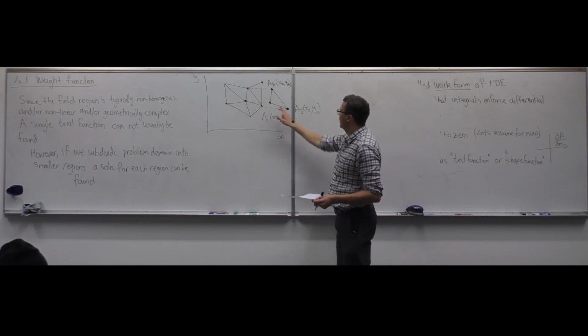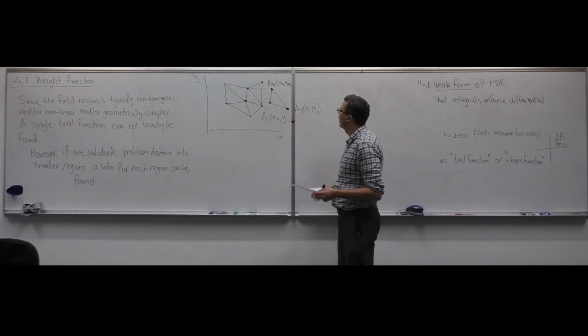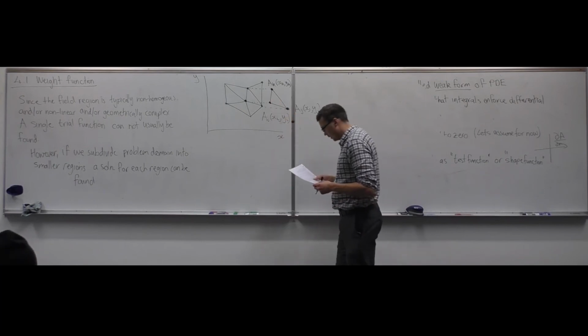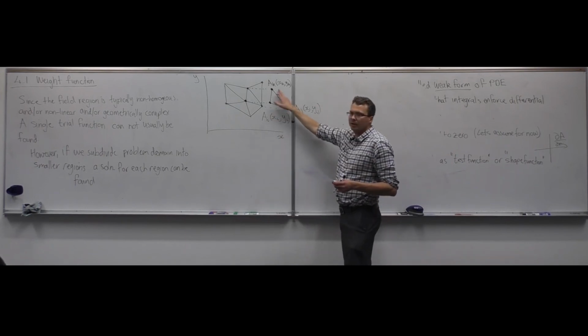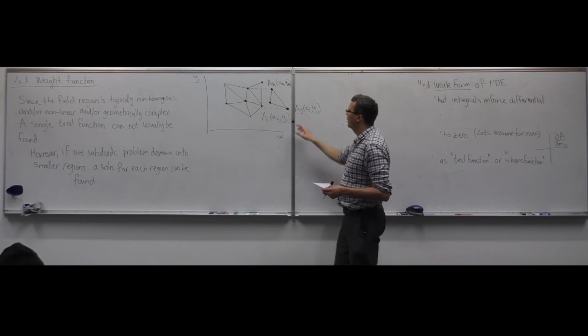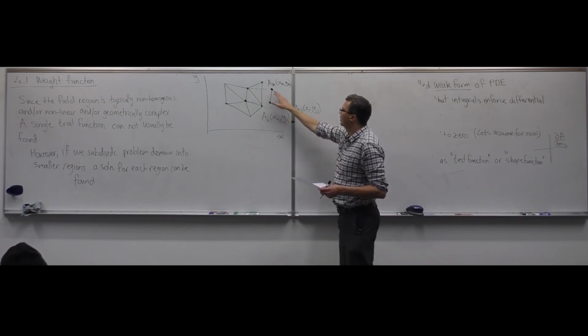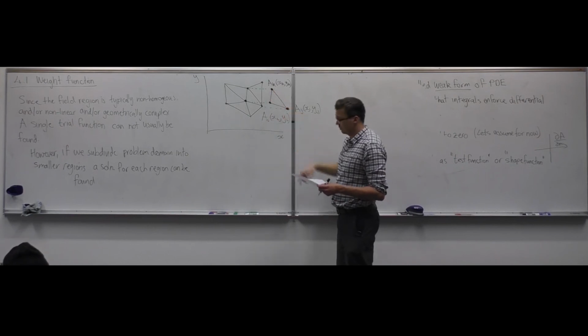So the xi and yi is a particular spatial location, and that will give a particular magnetic potential value. Okay, so at those 3 points, there's some value. So let's assume we know what those 3 values are at those 3 points. Okay, and we want to then use that information to determine what the value is within the triangle, given that we know the values at those 3 points.